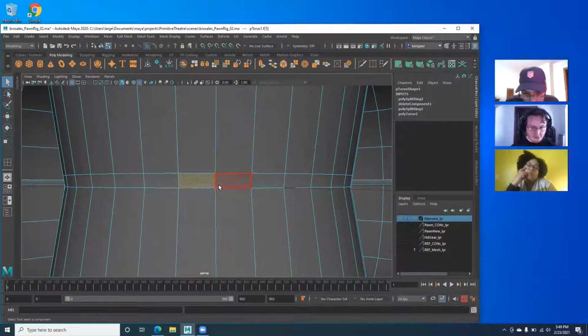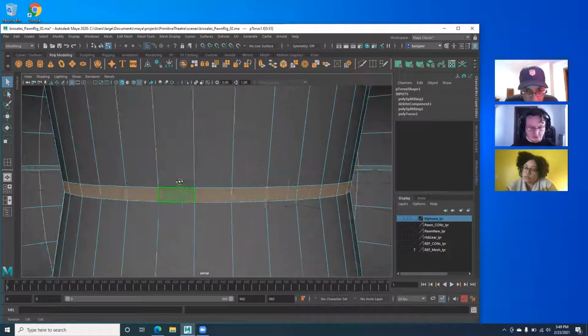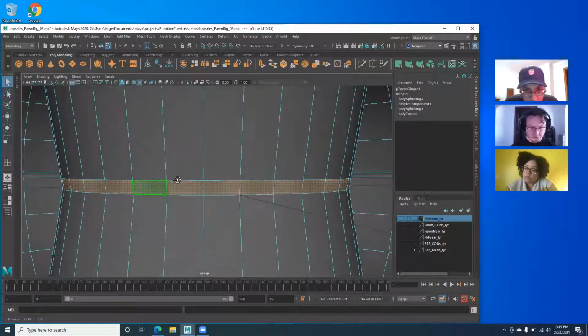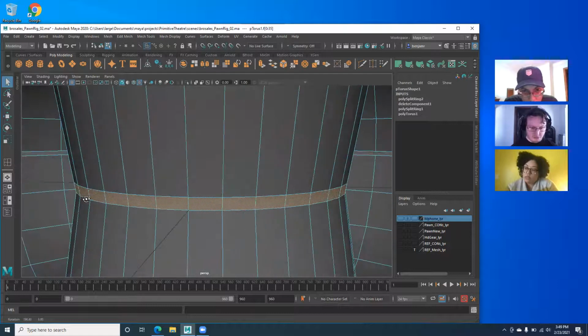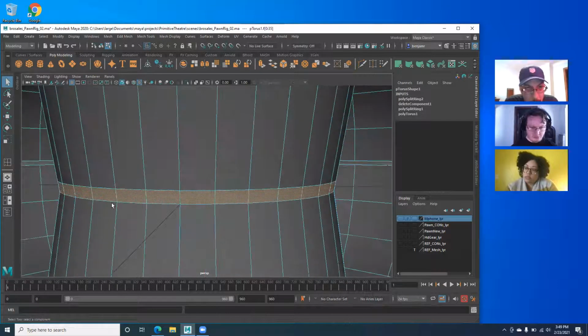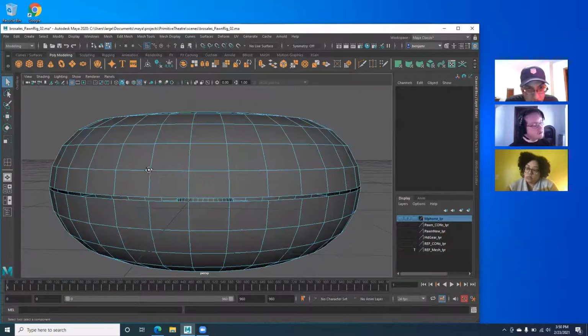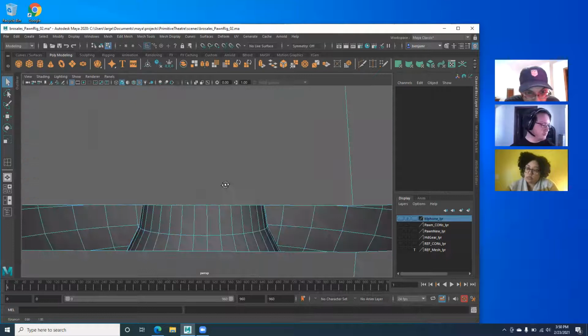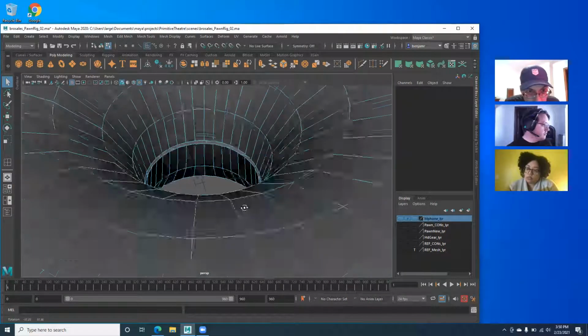to create edge loops. So I'm going to shift select, double click, and that grabs everything around the center. And I could have also offset it using the edge loop offset, but this does the same thing. So I'm going to delete that. So now I want to separate this geometry out.